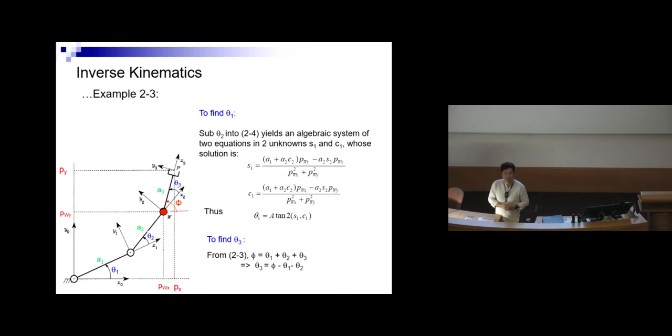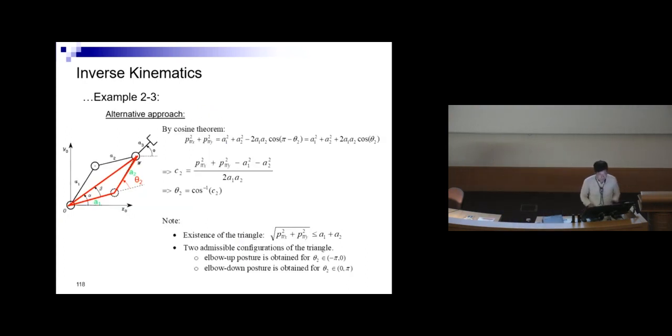So when you do all these inverse kinematic questions, you basically have to study the geometry and do the analytical method. But there's an approach over here, the general approach, meaning that you solve one parameter at a time, equating them, and the other one is you identify the wrist. You differentiate the wrist from the arm. It will actually help you in solving the inverse kinematic problem. So there are alternate approaches.